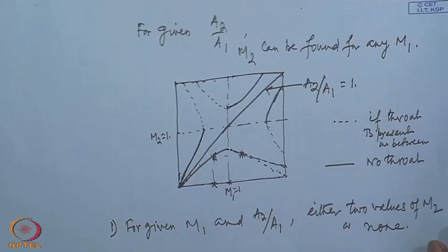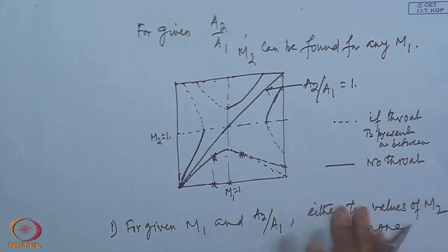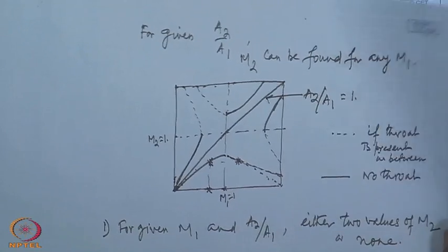The flow will initially be unsteady, there will be wave propagation, and finally it will reach a steady state, but with a reduced M 1, that is a reduced Mach number at the inlet, and a reduced mass flow rate. That is, it will enforce a change in the inlet condition. However, this new flow configuration can be maintained if the back pressure is also adjusted accordingly.